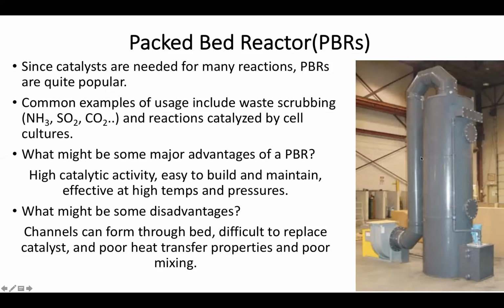Now, one of the other issues is you can have some poor heat transfer properties and poor mixing. However, a well-designed packed bed reactor should hopefully be able to avoid poor heat transfer, but it's really hard to avoid poor mixing.